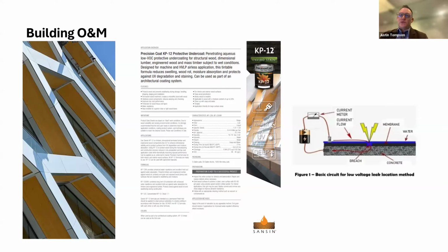But again, what this product will say is their warranty or their expected service life versus what they say it actually will do. They would never really put on paper how long it would last. They say it will actually last a lot longer than they're able to put on paper, but there will be a maintenance of that required at a certain stage. We did a lot of great detailing, as you see from the flashing along the edges there, to make sure that we've got returns, weather protection, venting, and membraning of that above on the roof deck. They're fully covered from wind-driven rain, but there may be some sun reflection that'll come off the windows. So in the service life of the building, they may need to be recoated.